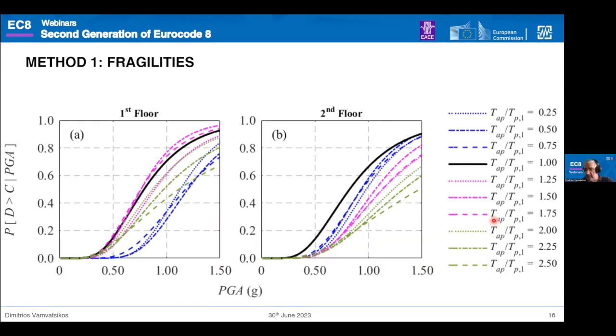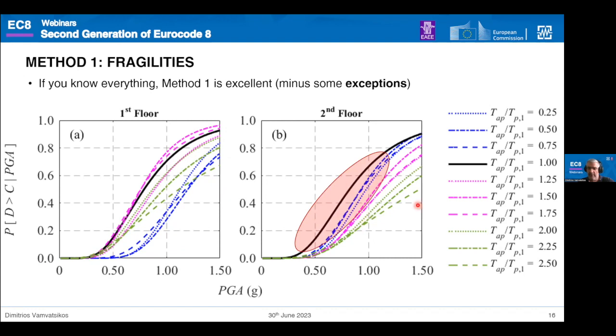Now, here are the fragilities, essentially the probability of collapse of, if you will, component damage in this case, which may lead to some leakage and fire, in terms of peak ground acceleration. And you can see that the black line is, let's say, our baseline assumption of resonance. Most cases, with some exceptions, in general, you have very, very good results. If you are in tune resonance, what you get is this pretty good value, which for the design value of our structure, is less than 10% probability of failure, which is even actually less than 7%. Remember it was around 0.24 g, maybe even times 1.5, 1.75. You're somewhere over here. So method 1 is doing quite well, even when you're in resonance.